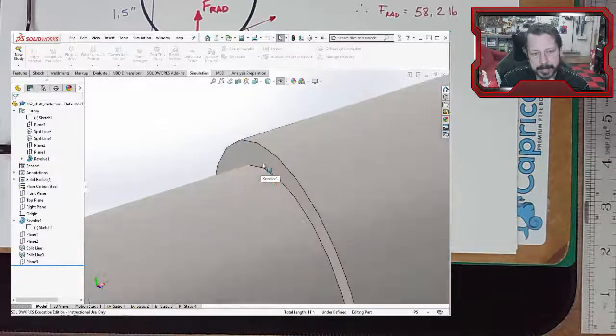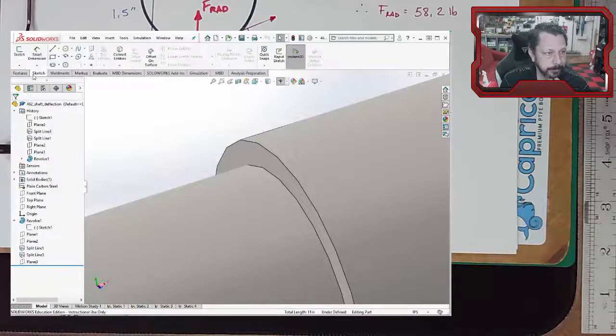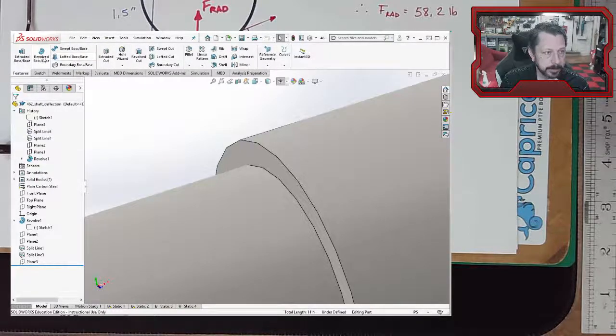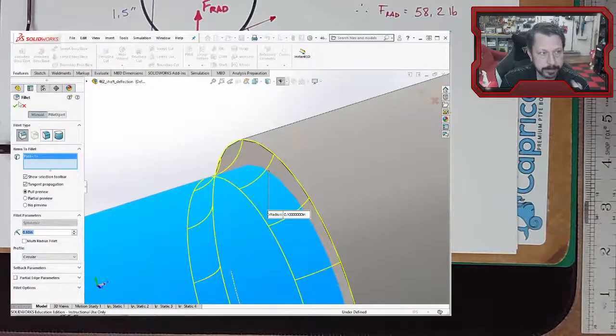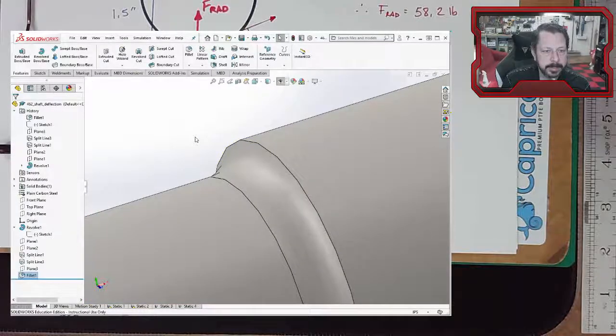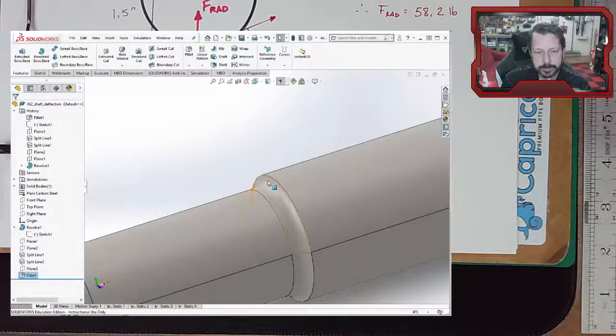But what can happen is if I put a fillet in here, let's put one. So if I put, that's way too much fillet, but if I put a fillet on there, now this curved surface, when I go to put those triangular tetrahedron elements to mesh it, they need to be smaller in here to account for this curve.